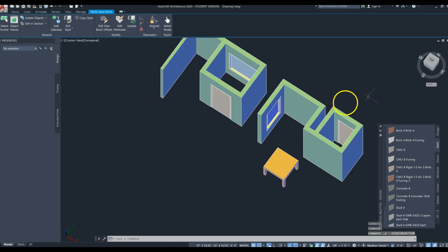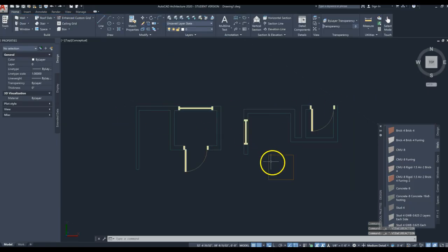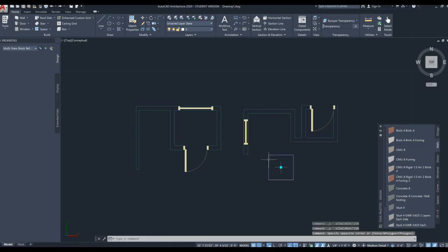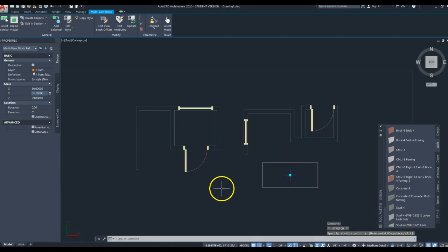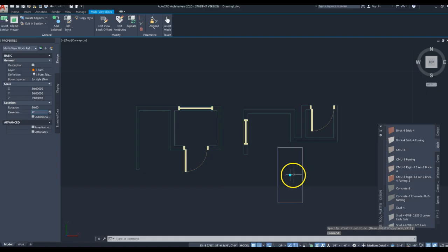Perhaps my table is, let's click it again. Maybe the table is 80 inches long, right? I can click here where it says X, type out 80, click Enter, and there's my 80-inch long table. I can click that square, the blue square in the middle, to move it around. And you can also rotate the table if you wish, under Rotation. Rotating works, that's fine to do. You can do 90 for a 90-degree rotation. There we are.